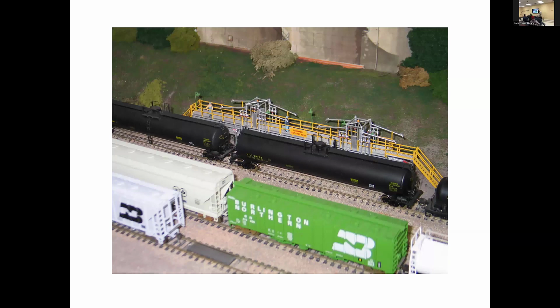Okay, so here's an example. We have a loading dock, and it appears we're going to load from the top, gravity filled, but I have pressure cars. Is that correct? Nope. These need to be low pressure DOT 111 cars, unless they're just stored there. I can't load gravity filled into the pressure cars. I've got to do hoses into the liquid lines, and I've got to have a vapor line to take off the gases so it doesn't collapse.